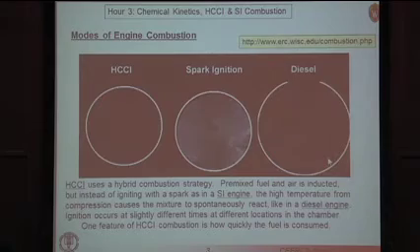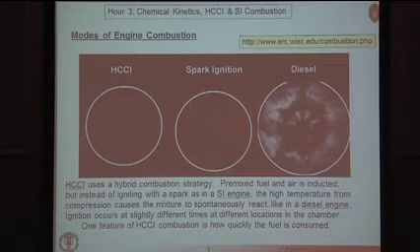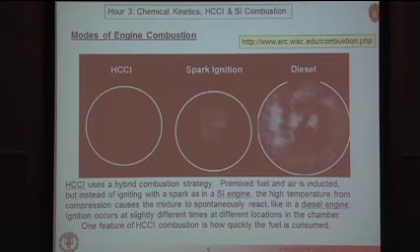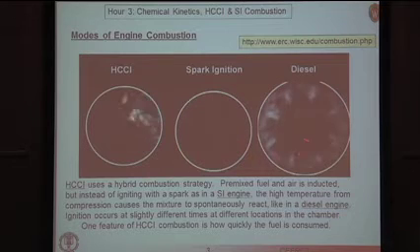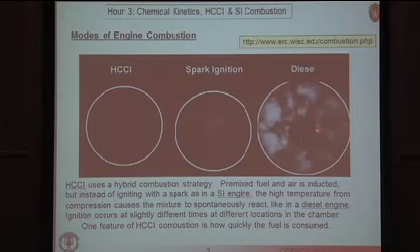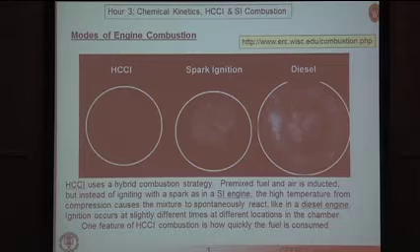Let's see if I can show that again. So these diesel jets, for example, lead to a very poorly mixed mixture of fuel and air. Looking at the diesel jets here, they still auto-ignite, and one has then combustion taking place over a range of local equivalence ratios.